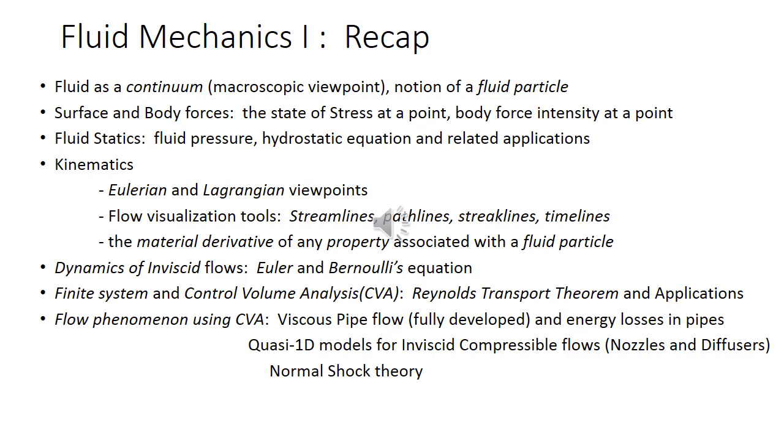Now this is very important because from the point of view of application of physical laws to a particle, whether it's mass conservation, Newton's second law of motion, which you also call the momentum equation, or maybe even thermodynamics laws, when you apply them to a particle, these laws naturally involve the time rate of change of certain properties associated with that particle. So that time rate of change of any property associated with a fluid particle is what you call the material derivative, and we can express it in terms of Eulerian fields that we already know.